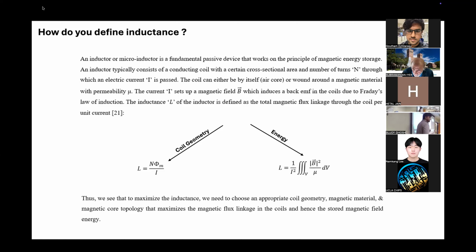This is also the fundamental reason why inductors don't scale like capacitors. In a capacitor, you can increase the capacitance density just by bringing the two plates close to each other, increasing the area, and then crumpling it up into a suitable form factor. That's what you do in a deep trench capacitor: you take a large sheet, reduce the thickness between the plates, and push that plate into a hole so that you have this over a smaller effective area. But in an inductor, that's fundamentally not possible, because to increase the inductance you need to increase the magnetic flux density per unit volume. So it scales with volume versus area. That's the reason why on-chip inductors are not even close to as good as on-chip capacitors.